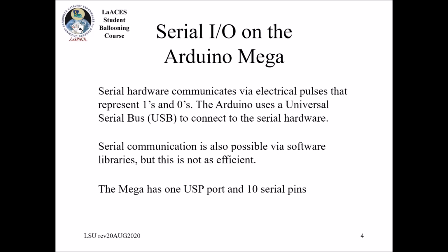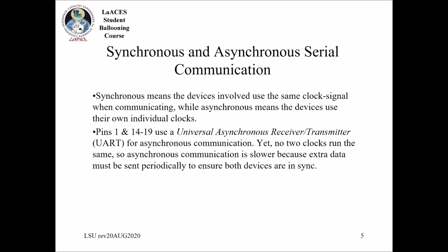The Mega has one USB port, I'm not sure if it's a different protocol, and 10 serial pins. Point being, there are many options on this board for different serial ports, so if you want to communicate with multiple devices on different serial ports, you have the opportunity to do that.